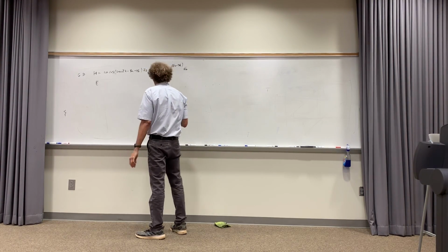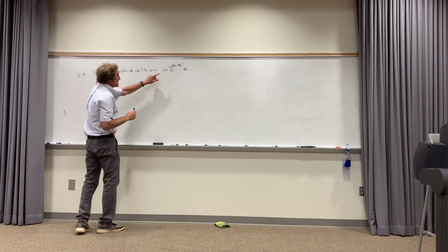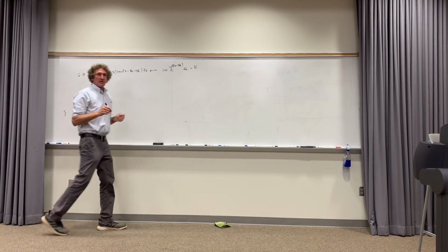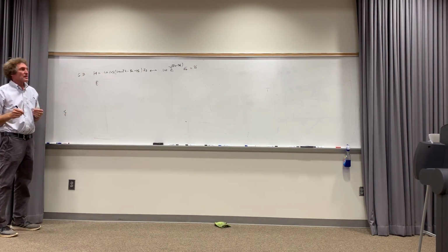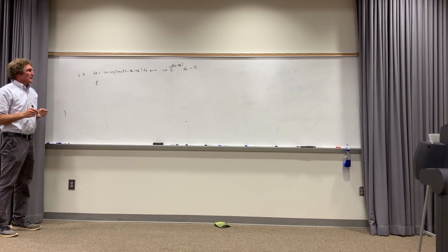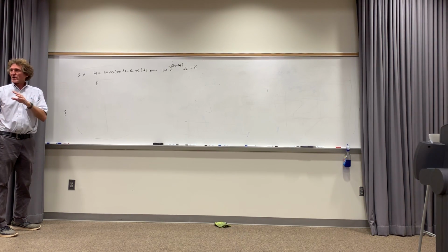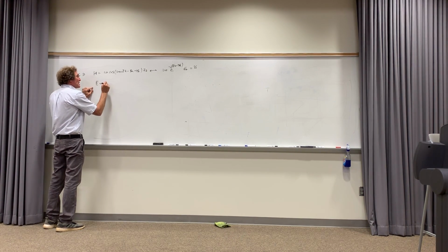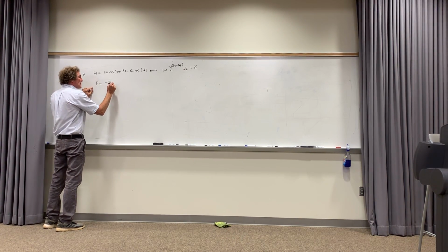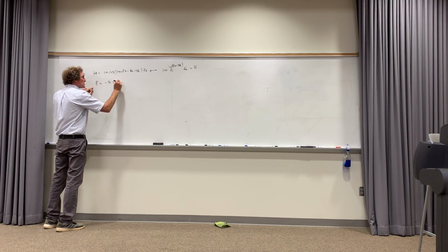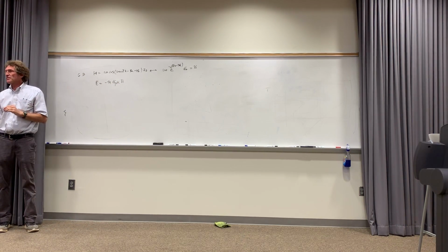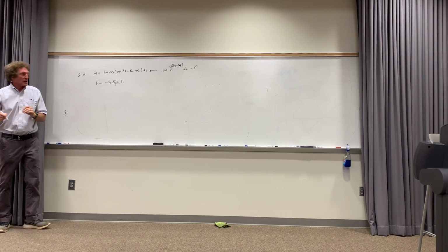Now, when we look at these two, this is again time domain, that's phasor. So this would be H bar, or H tilde. And it's a vector. Now to get the E field, we can do it in the phasor domain. E, remember, was equal to what? It's minus eta, right? Then it's going to be times the direction of propagation crossed into the H field. You remember me showing you that last time, class? This is in the phasor domain you do this.